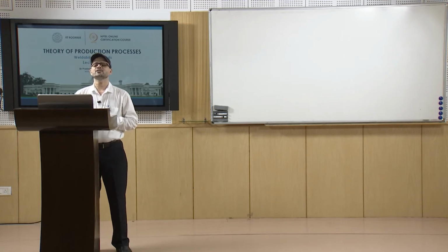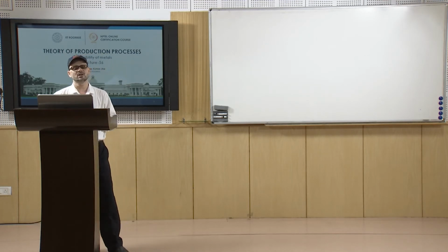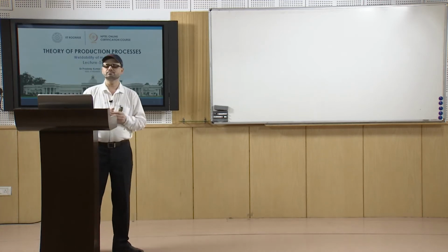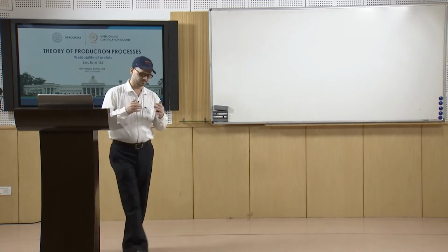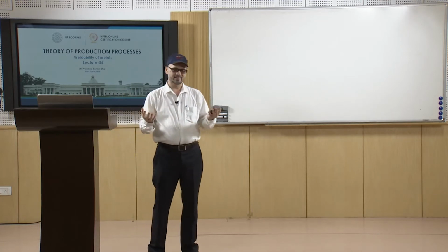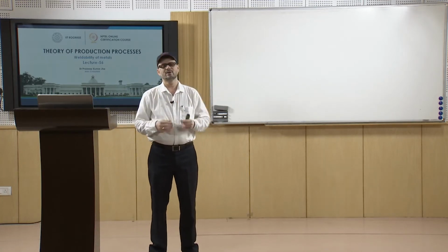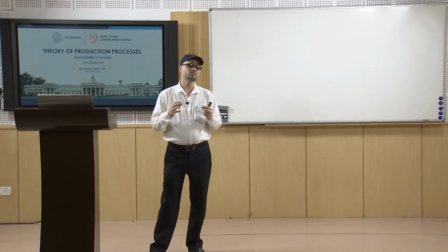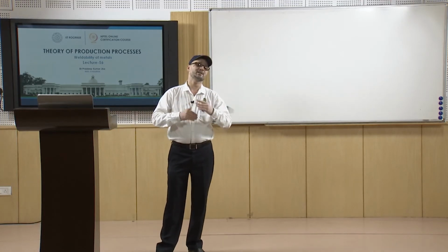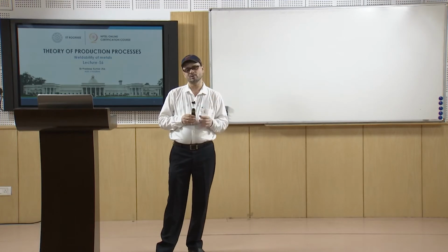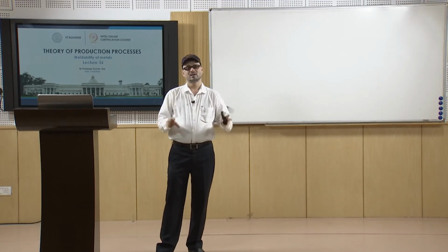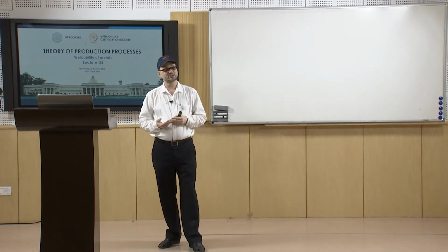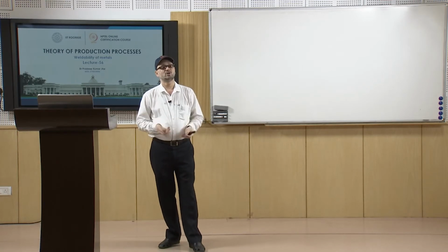The second point is mechanical soundness. Mechanical soundness means that the material which you are welding, and in that weld pool when you have the solidified weld, should be mechanically sound, because ultimately the mechanical properties will depend upon the absence of impurities, or the absence of blowholes, cracks or defects.